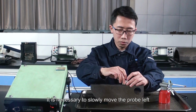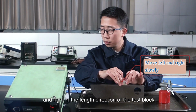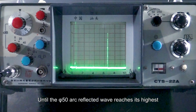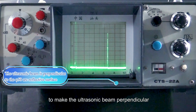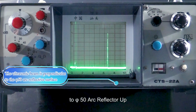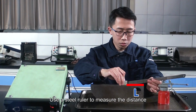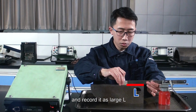It is necessary to slowly move the probe left and right in the length direction of the test block until the R50 arc reflected wave reaches its highest, that is, until the ultrasonic beam is perpendicular to the R50 arc reflector. Use a steel ruler to measure the distance from the front end of the probe to the edge of the test block and record it as L.